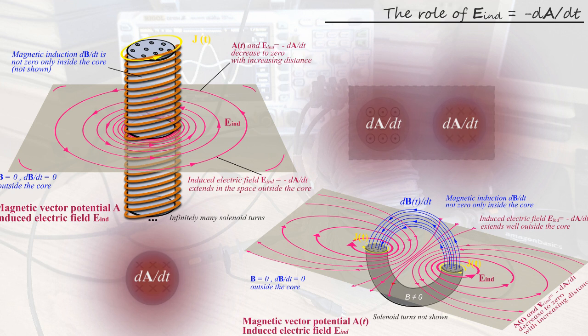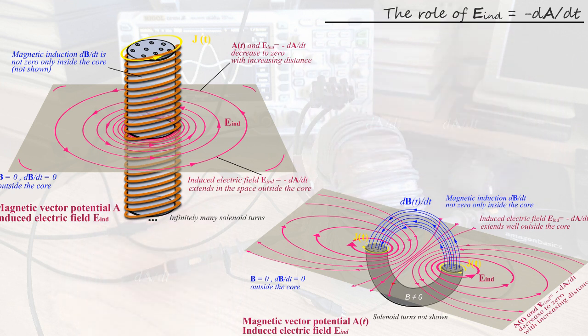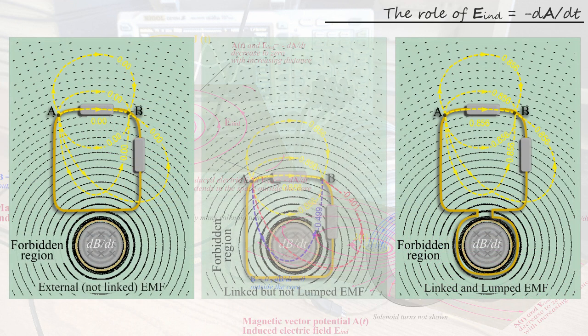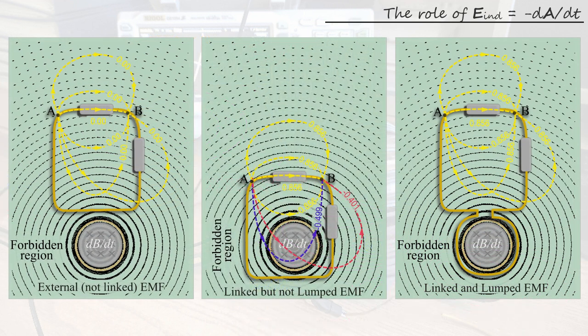After all, this is the field that is responsible for rearranging the configuration of charge inside and on the surface of the conductors that reside in the space around the source. The surface and interface charge displaced by this field will in turn generate the Coulombian field, E Coulomb, responsible for the scalar potential difference component of voltage.